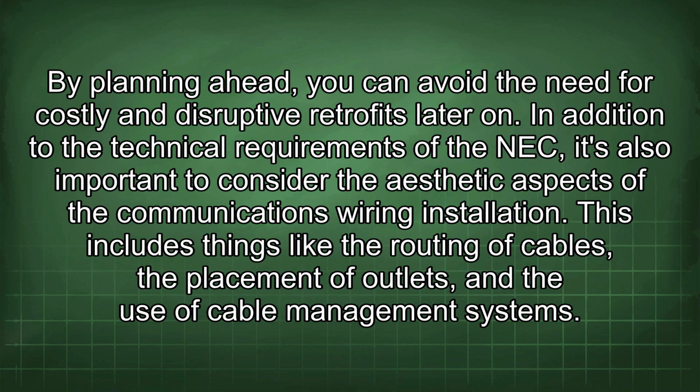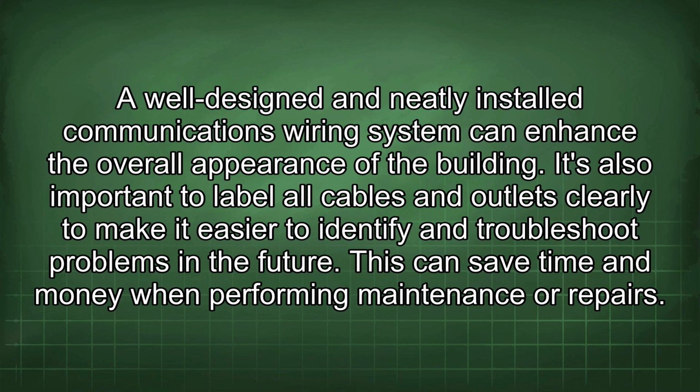In addition to the technical requirements of the NEC, it's also important to consider the aesthetic aspects of the communications wiring installation. This includes things like the routing of cables, the placement of outlets, and the use of cable management systems. A well-designed and neatly installed communications wiring system can enhance the overall appearance of the building. It's also important to label all cables and outlets clearly to make it easier to identify and troubleshoot problems in the future. This can save time and money when performing maintenance or repairs.